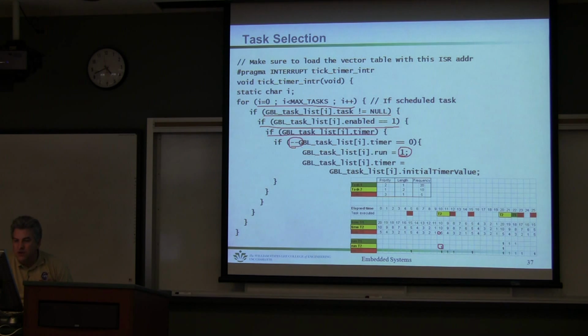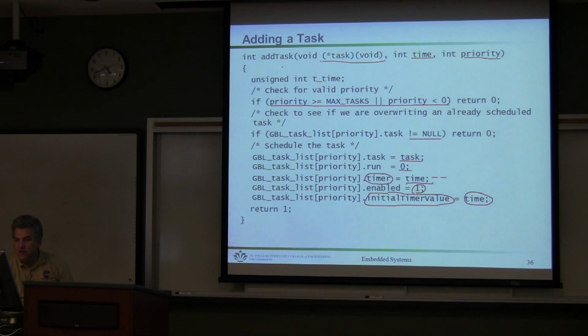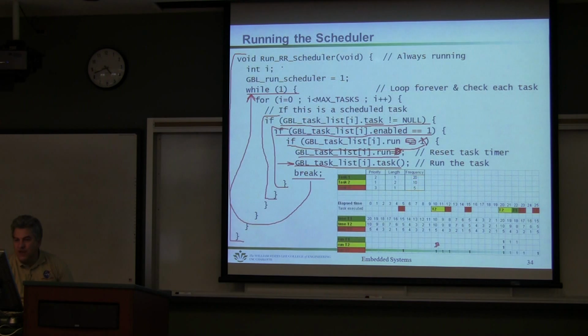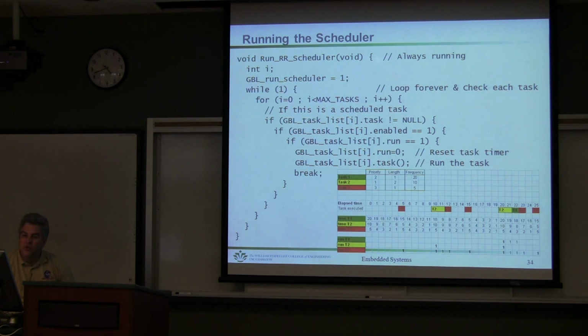Remember, it was at 0 because of this line, and now you change it back to 5. And this is done in the interrupt service routine, so no matter where the interrupt service routine is, as soon as you return, you will go back to running this major loop. And you will, of course, at this point probably be running right here. You will finish executing whatever it previously was, or if it was idle, it's just going through this loop.